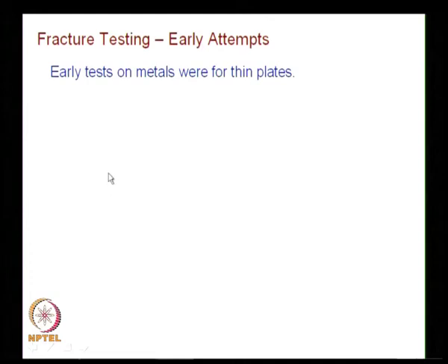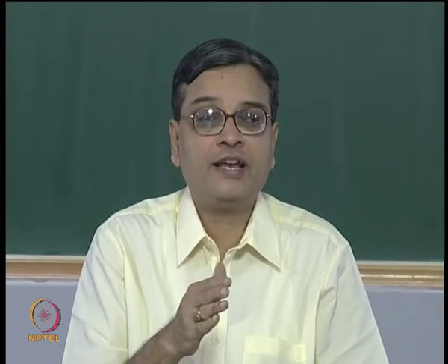And you should also note, after the tests on acrylic sheets, the scientific community did tests on metals that were for thin plates. They are not really tested thick plates, though we had discussed as an extrapolation of modeling of plastic zone, to maintain plane strain condition, I need to have an appropriate specimen thickness.